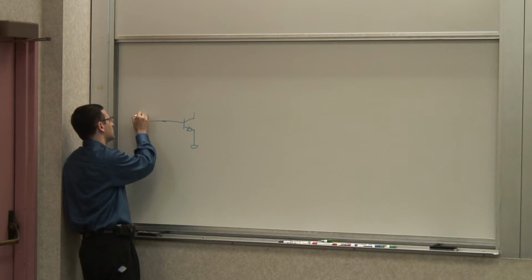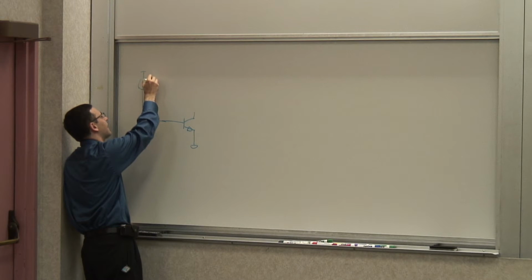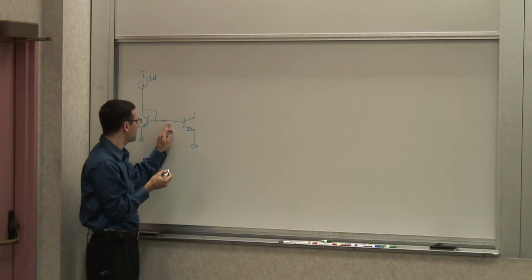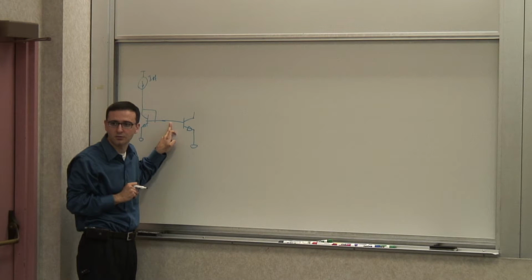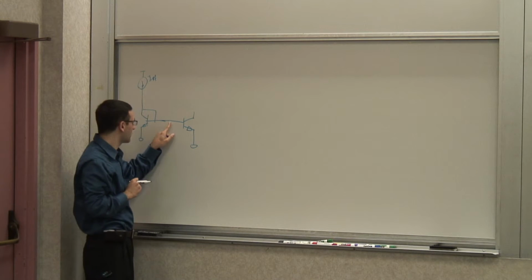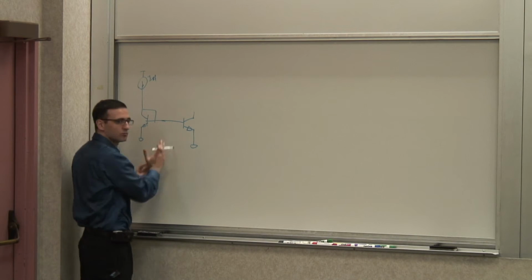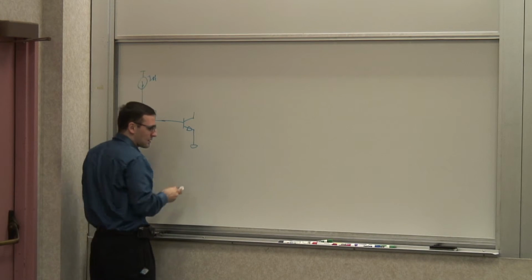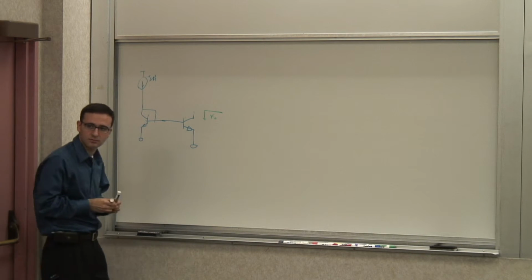And so the basic current here, if you look at it, looks like that. Now, this is a basic common emitter whose base voltage is kept at a constant voltage. You remember I said I would tell you somehow how we maintain these base voltages? This is one way to get the right base voltage, to bias it at the right voltage. That's exactly what I'm doing. This box is that simple version of that. Now, the output impedance, looking into the collector of this thing, is RO of the transistor in this case.